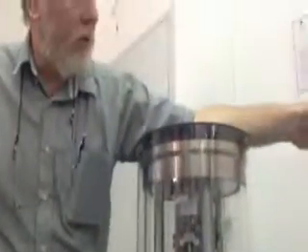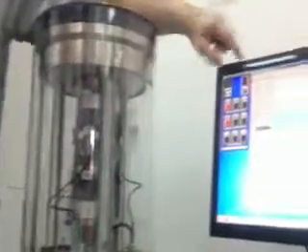So if you go back to setup and control, here's the frequency range the machine can operate, from 25 Hertz up to 0.1 Hertz. Which frequency? We'll need to check the current standard. I think it calls for 3 or 5 frequencies. You may wish to run all frequencies depending on what you wish to do. So the software is flexible. You can untick a frequency so it won't run that frequency.